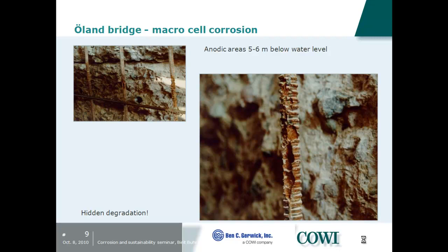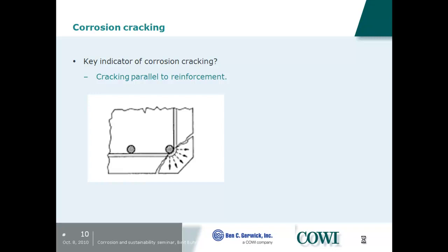We know from many of our existing structures that we actually have corrosion underwater. What we don't know in detail is what is the water-cement ratio on the concrete and the chloride ingress parameters, but we can avoid these. But normally on new structures, we know with very low water-cement ratios, we don't expect this.